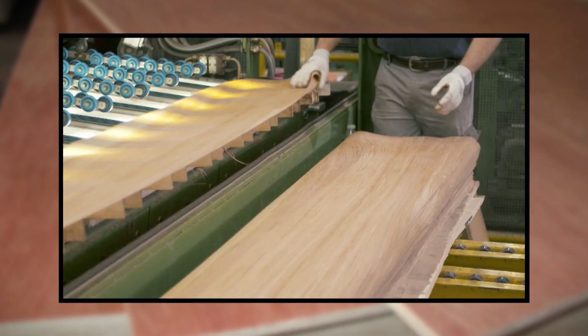In any case, the next process involves cutting the veneer into usable widths. At the same time, optical scanners look for sections with unacceptable defects, and these are clipped out. The sections of the veneer are then sorted and stacked according to grade. The sorted sections are fed into a dryer to reduce their moisture content and allow them to shrink before they are glued together. Let's now learn about forming the plywood sheets.